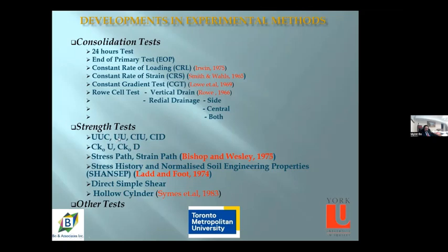However, soil in situ is confined under the stress of the surrounding soil. Because of that, this UC test may not be representative of the in situ condition. That's why they developed the unconsolidated undrained test, but the specimens are confined under isotropic water pressure.